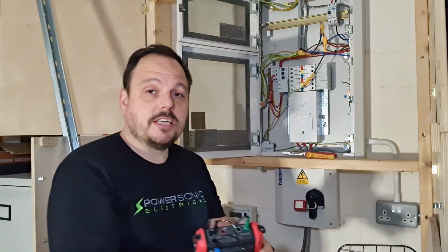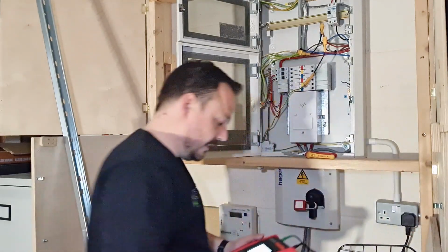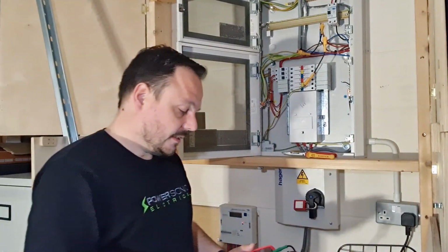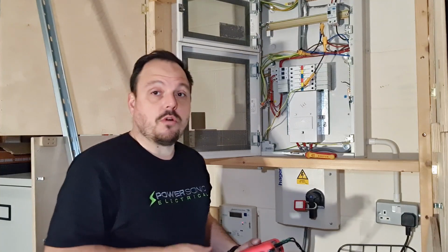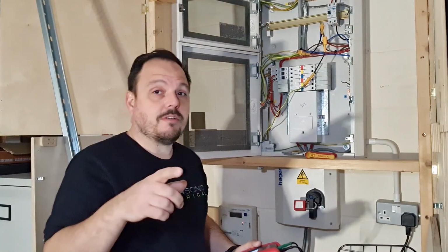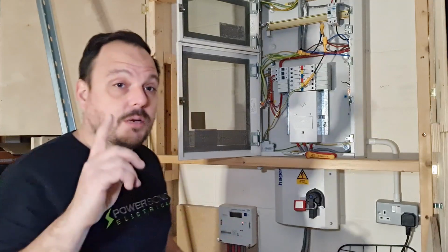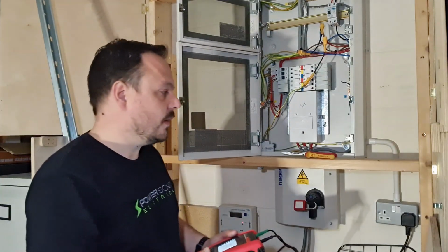There is a little handy socket here at the side of the distribution board, so I can gather an R1, R2 off this, and if I hit test, it's coming out at 0.13. Now I've already been over the other side of the office and checked that, but I'll just spin you around and you can have a little look at me doing it. I'll get it set up for when I'm going to do the lighting circuit. Saves messing about with the camera. So I will show you me getting that at a couple of other sockets as well.